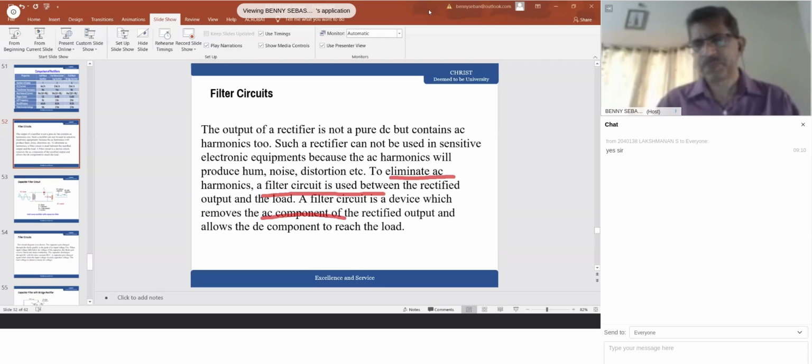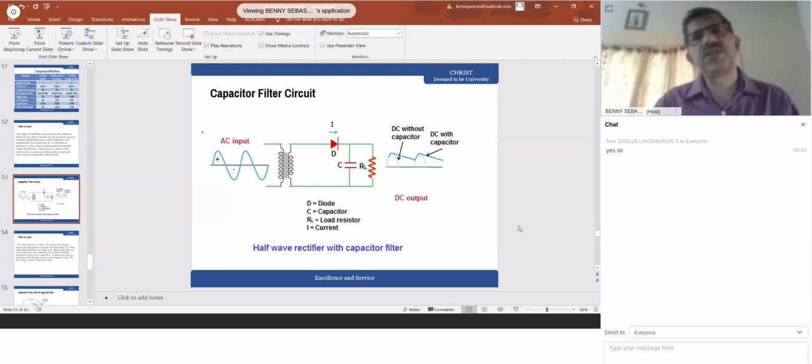So we saw the theoretical aspect, how the capacitor is capable of doing that. Hope we have gone through how the capacitor has a property. What is the basic property of the capacitor? It will allow AC to pass through. It will block DC. So therefore, you are putting this in a parallel format now. So the capacitor filter, we call a shunt capacitor filter.